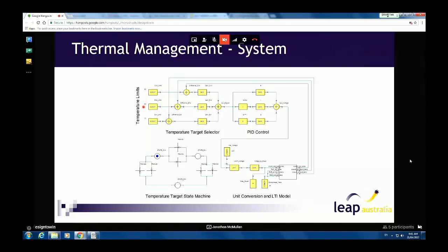The outside temperature of the enclosure is about 65. We judge this to be safe enough that you can put your hand on it and not be burnt too quickly. And we have an exhaust temperature limit which is slightly higher because we don't anticipate you sticking your fingers in through the exhaust of the fan. So each of these are separate, and we only have one PID controller here. So we've obviously tuned this PID controller to react at an appropriate speed to the system.